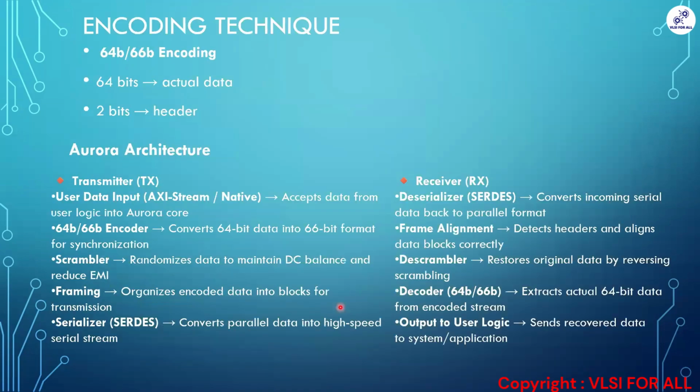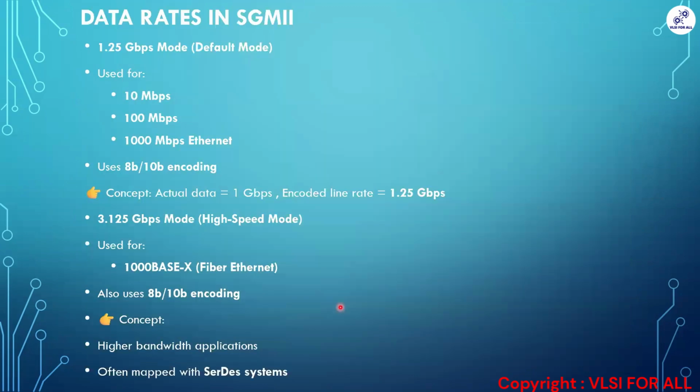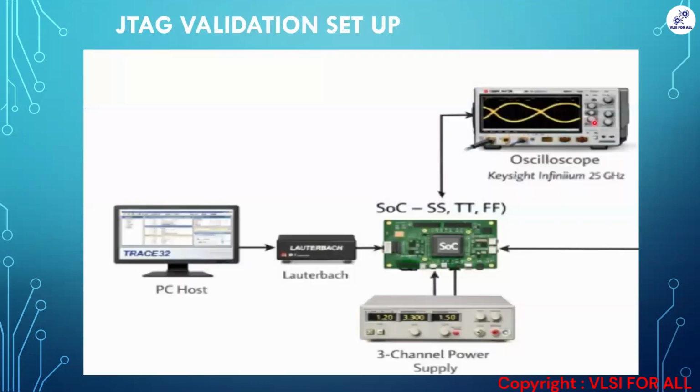We have eye diagram options on this oscilloscope, like bit error rate we need to measure. First, we see the bit rate measurement. Using that, we go to clock recovery, and using that clock recovery, we set the amplitude of the eye and the width of the eye.